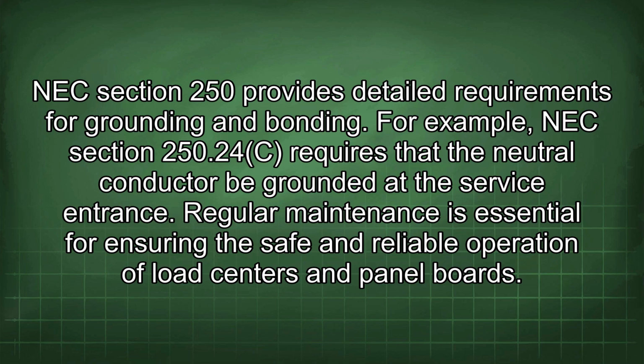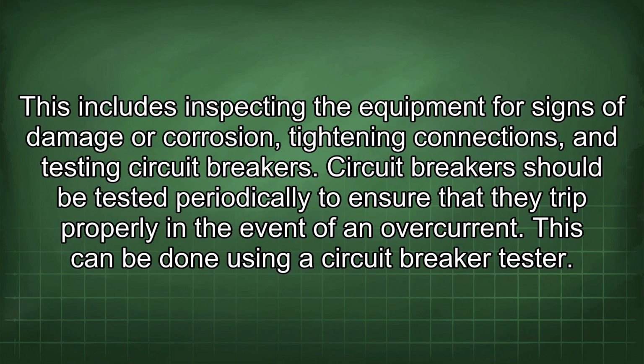Regular maintenance is essential for ensuring the safe and reliable operation of load centers and panel boards. This includes inspecting the equipment for signs of damage or corrosion, tightening connections, and testing circuit breakers. Circuit breakers should be tested periodically to ensure that they trip properly in the event of an overcurrent. This can be done using a circuit breaker tester.